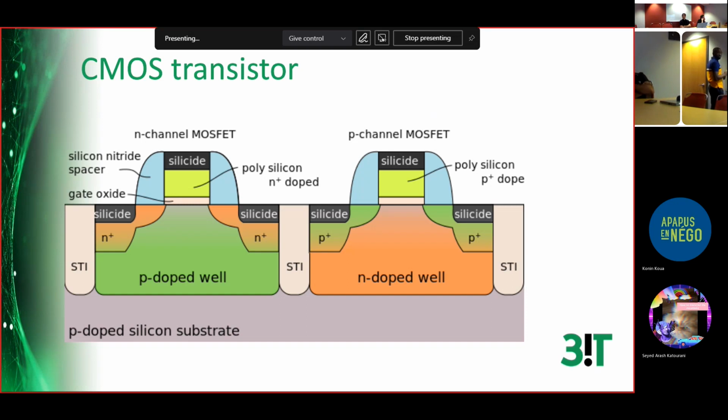Let's stay with STI. I'm just explaining the fact that this is a continuous area. So how do you add dummy? The STI is always at the end of the OD region. When you add dummy, the dummy will be here.